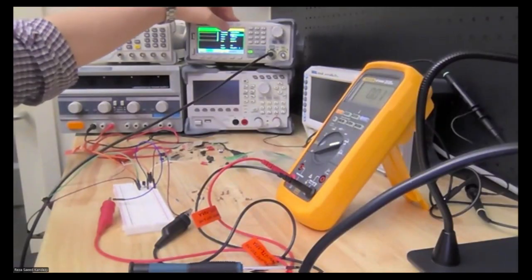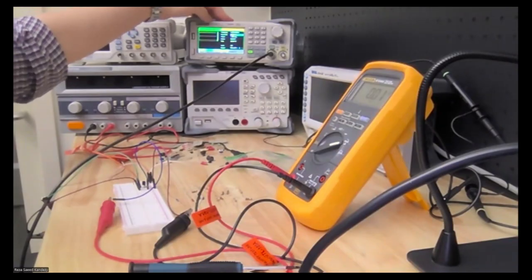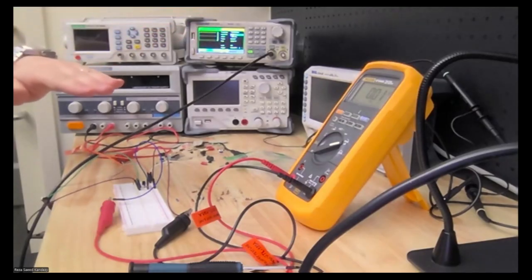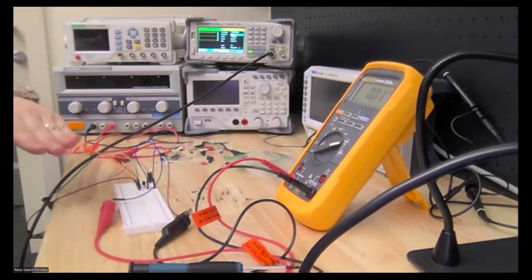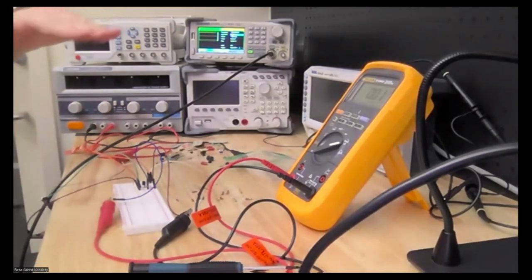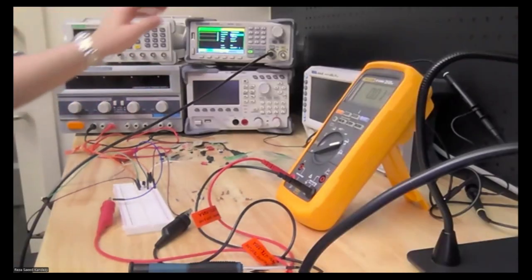When you say 1 volt, on the function generator this is 1 volt peak to peak, so the function generator would create a signal from minus half to plus half. So you need half of the voltage as an offset. So you have now from 0 to 1 volt, and when you have 100% duty ratio, it's basically a DC signal.